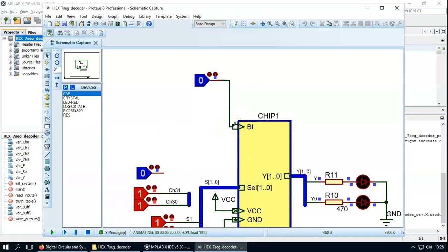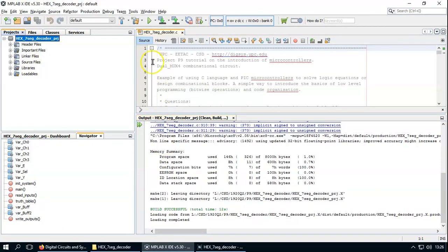But that is not your problem yet. But let it be like that, okay? Just reading the blanking input so that we can convert this pin into a convenient RAM variable to be watched in the watch window. So now you can stop, because everything has gone right. You can stop the simulation, and you can go back now to the software environment.